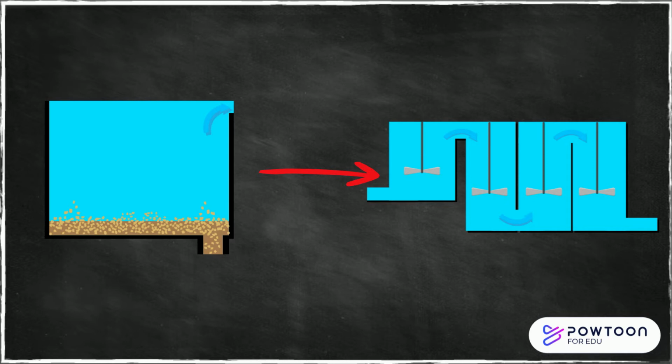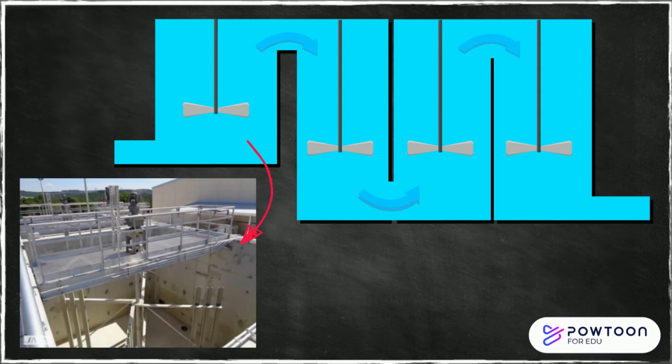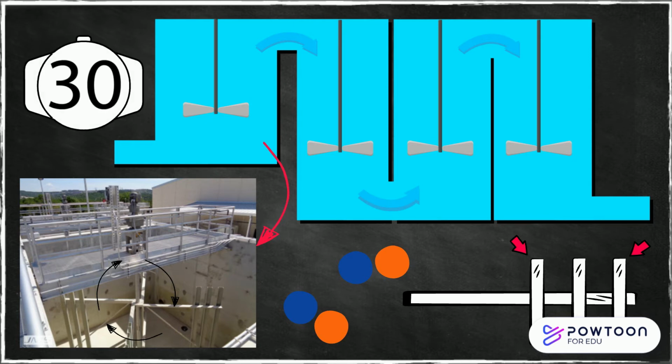This produces a dense floc that will eventually settle out. The flocculation tank typically uses a paddle wheel. Basically, it's a rotating arm with 3 paddles that go at different velocities. The paddle wheel pushes the water to differ the collision rates. The outer paddle moves faster and dissipates more power than the inner paddle. Typical flocculation tank times are about 30 minutes.